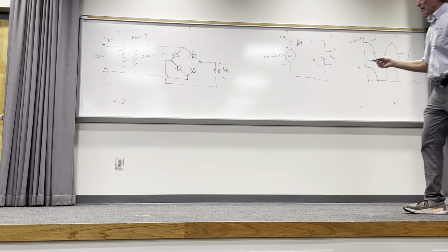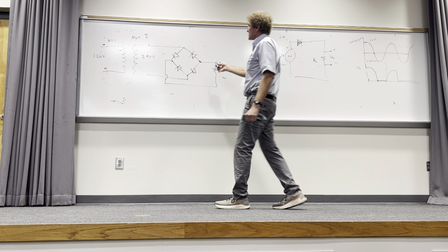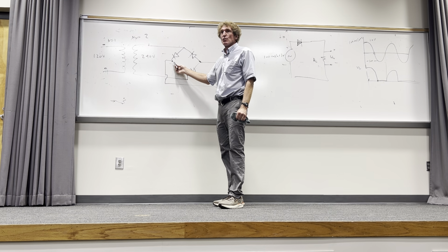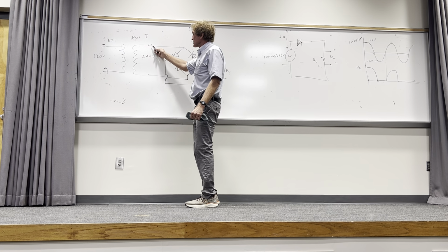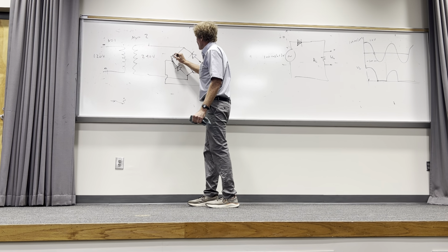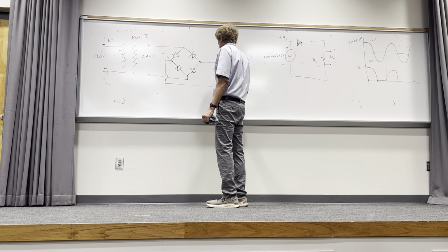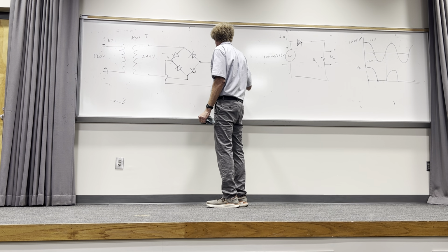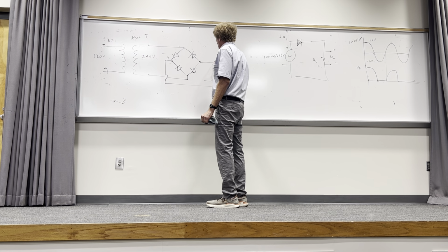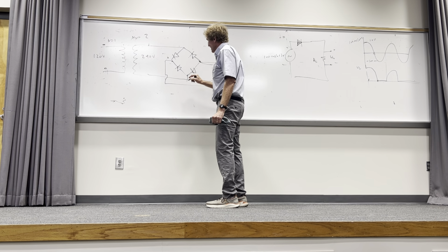Now, and I'm not going to have time to do this, this particular circuit will do full wave rectification. When this is positive, this is negative, current will flow this way here, this will become positive. It'll come through here, and I actually drew this wrong. This is drawn upside down, but this is plus minus. This would be positive, current would return here through this.